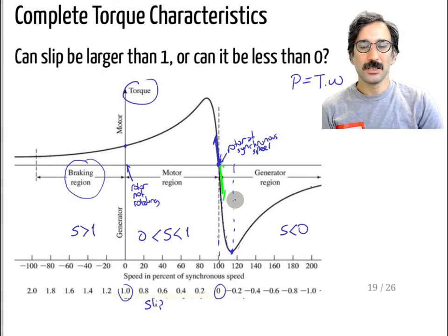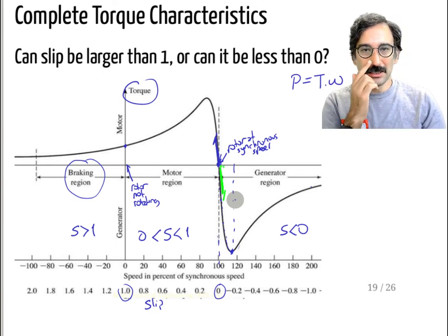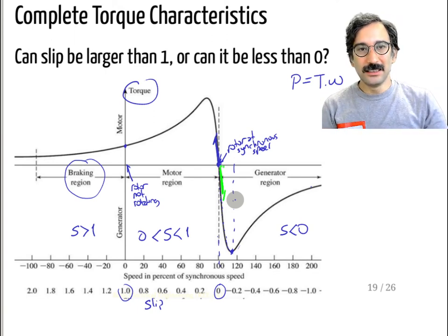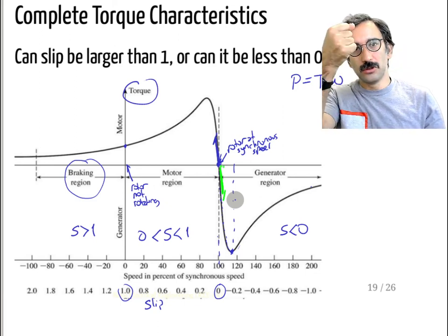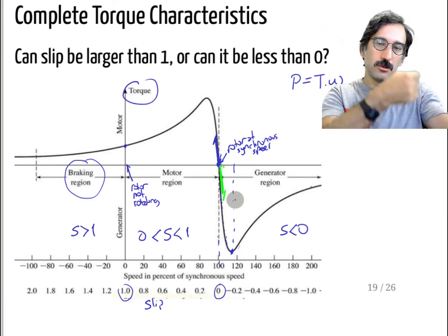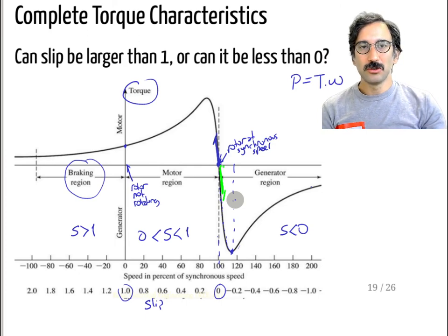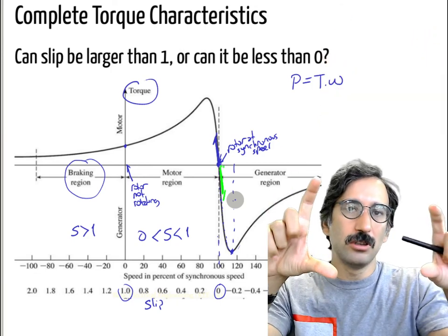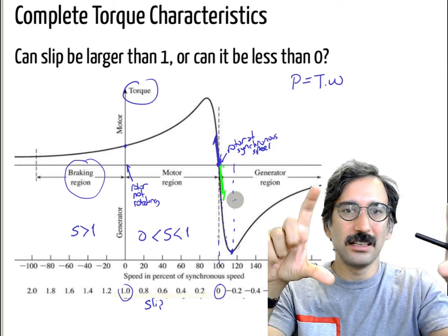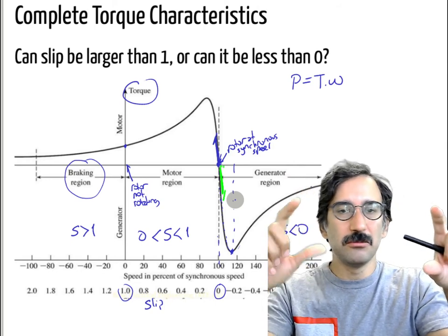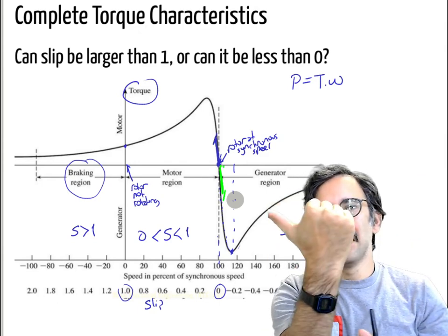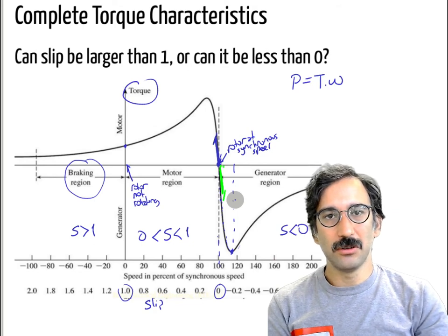Remember, in the synchronous machines, the motoring and generating mode depends on the loading angle. So whichever is leading the other, if the rotor is pulling the stator MMF or the stator is pulling the rotor MMF, then you will be in the motoring or generating mode. In the DC motors, remember, you have the back EMF, EA, you have the terminal voltage, and if that terminal voltage is higher than the back EMF, EA of a DC motor, then energy flows in that direction. If it is less than EA, then the current flows in the opposite direction.